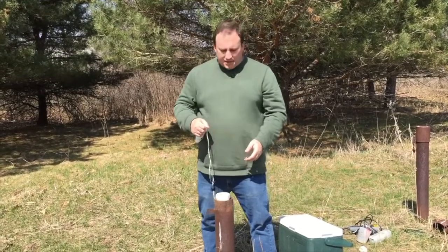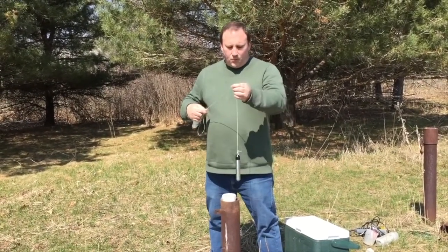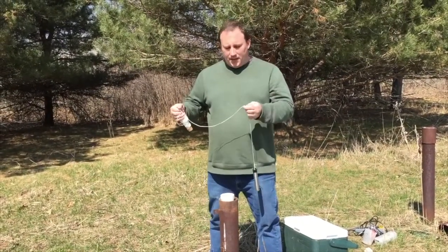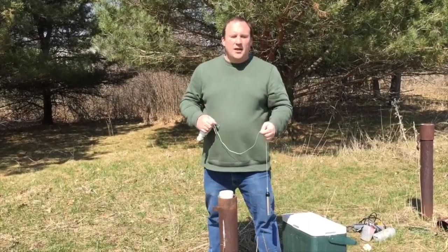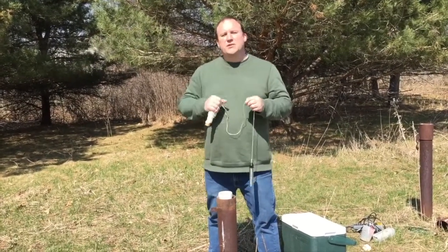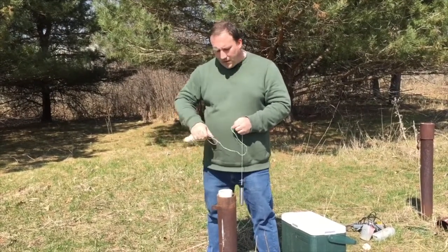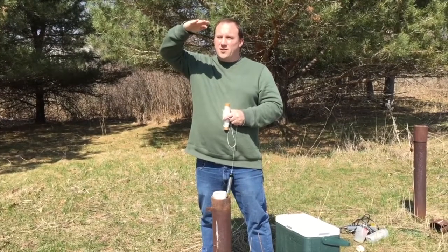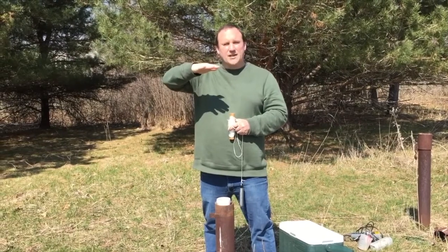I could be monitoring this with my water level indicator. It's not really that important. What I will do in this case is I know that this is a 42-foot deep well, and I can feel where it's going to hit the bottom. I'll let it touch the bottom, and then I'll bring it up a couple feet just so it's hanging off the bottom. That's going to be well below any area where the slug is being lowered. So the top of casing is here. The top of the static water level is 11.34 feet, or whatever I said before.